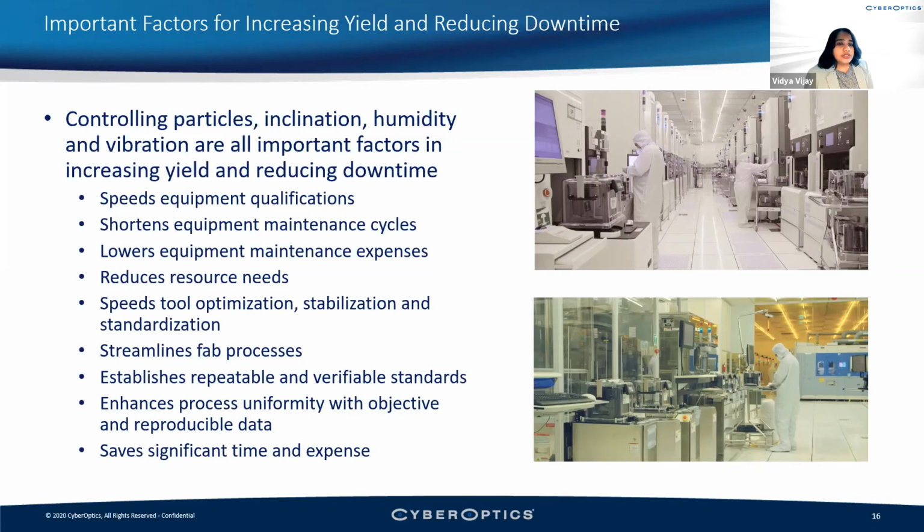It also reduces resource need. Before the wireless technology, customers had to move and open up tools. The majority of the tools run hotter, so you're waiting for the tool to go down in temperature. You're waiting for the tool to pump down to be at atmospheric pressure. We still have to cool down for our sensors to be in the tool, but at least you don't have to open up and re-clean and look for particles again and so on. All of this can happen with the tool intact.